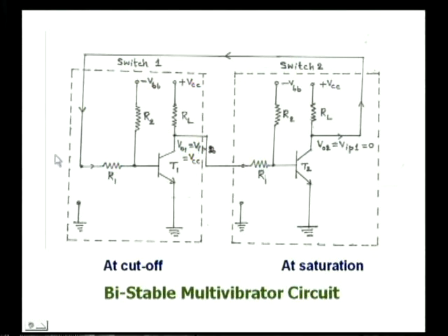So this VCC will be applied to the input of transistor T1. So here it will be VCC and this is minus VBB. As previously discussed, the potential divider R1 R2 can provide a positive bias to the base emitter junction of T1 so as to make it on, and with T1 on, the output will be 0, which will keep the reverse bias voltage across transistor T2 and hold the transistor T2 in off state.